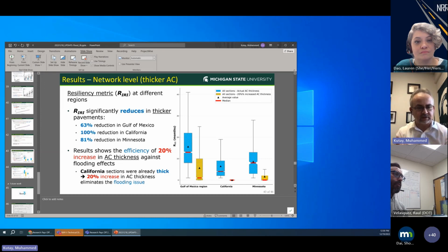So that might be the reason for California. Increasing the thickness helps in spreading the load a little bit. You can think about it like a snowshoe. Of course, the downside is you might have a heavier pavement above. I don't think there's a model there that considers that much. This is modeling, not necessarily a field study of actual data.